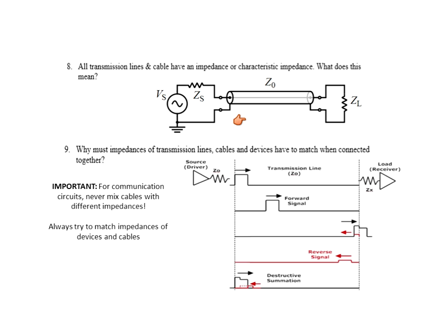Why is it very, very important? Well, you have to match the impedance of the cable to the device it's connected to. If it's connected to a receiver over here, that receiver will have an input impedance. That's the impedance of the load. The impedance coming out of this cable right here has to match the impedance of the load to get proper power transfer.